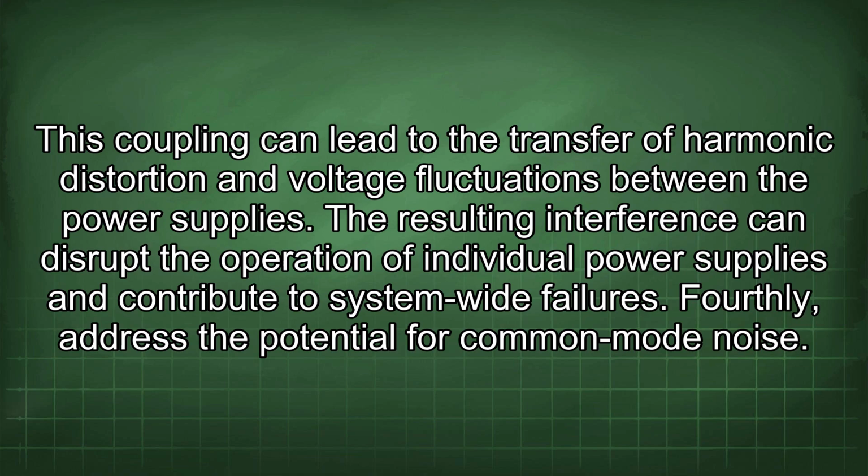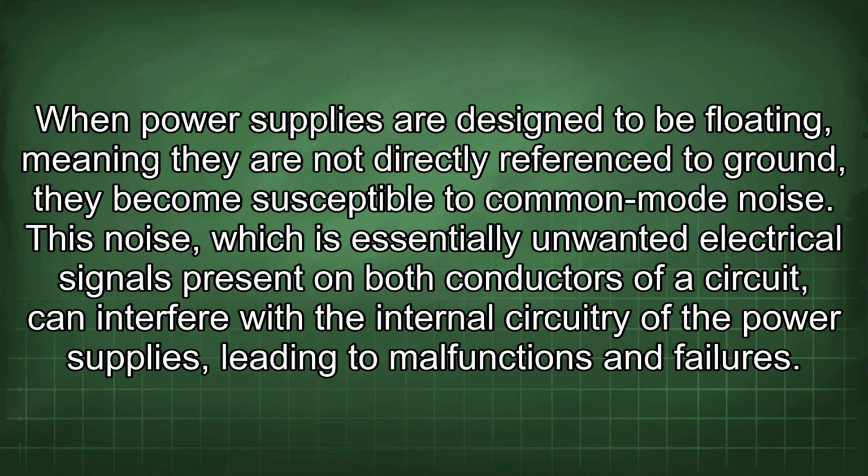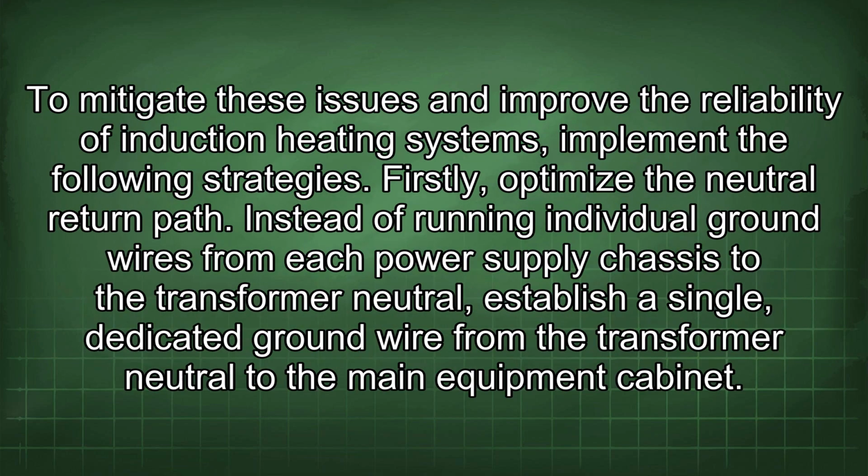Fourthly, address the potential for common mode noise. When power supplies are designed to be floating, meaning they are not directly referenced to ground, they become susceptible to common mode noise. This noise, which is essentially unwanted electrical signals present on both conductors of a circuit, can interfere with the internal circuitry of the power supplies, leading to malfunctions and failures. To mitigate these issues and improve the reliability of induction heating systems, implement the following strategies.